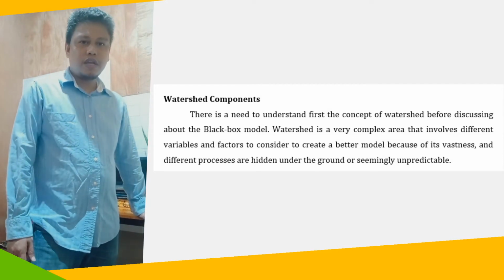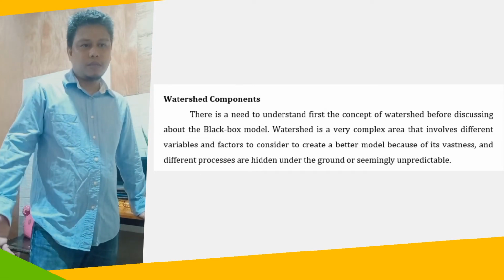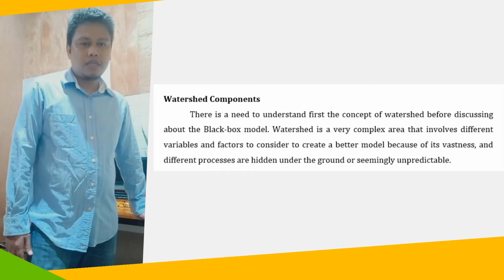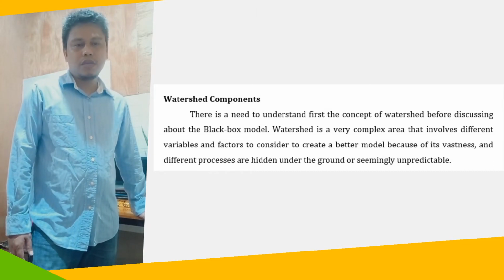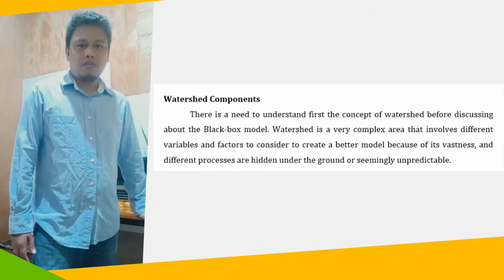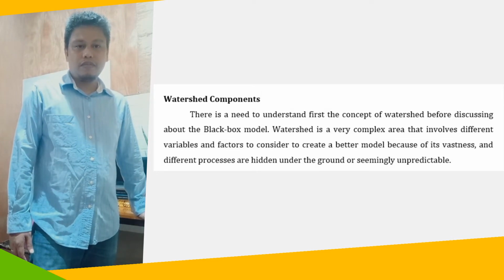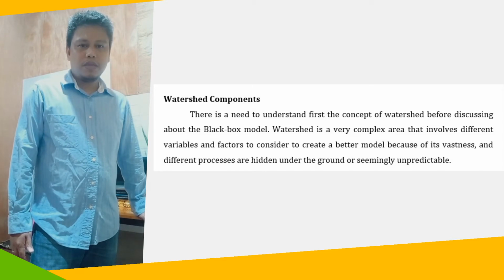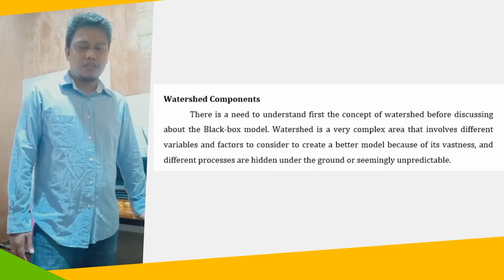Watershed is a large area of land that drains water from precipitation or from man-made consumption, including sediments and dissolved materials, to a common receiving body of water or outlet, such as river, sea, lake, catch basin, or reservoir. Watershed may usually cross political boundaries or administrative regions.